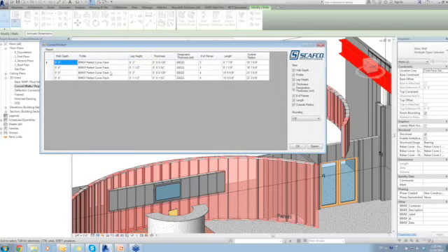It's telling me the web depth of all my members, the profile, so my curved track, the leg height, its thickness, it's in inches here. I would use the designated mil thickness instead. And the number of pieces I need to order at what specific length, and the outside radius.